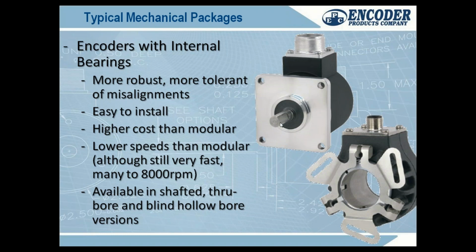So that way, even though there's vibration or run out, we are going to have that disc distance to the reed head maintained. Now, shafted encoders generally take a lot more shaft load. This model in the picture here is the model that takes 80 pounds axial and radial. So they can take a lot more of a beating. Generally speaking, if you have a lot of vibration on a shaft, I recommend running with our shafted encoder and then choose an appropriate coupling. We sell helical couplings, but there's other options out there. I've seen Lovejoy's used with a spider if there's a lot of axial end play in and out. Couplings are a whole science in themselves, but you'll want a coupling here to just isolate that shaft from the vibration of your shaft.